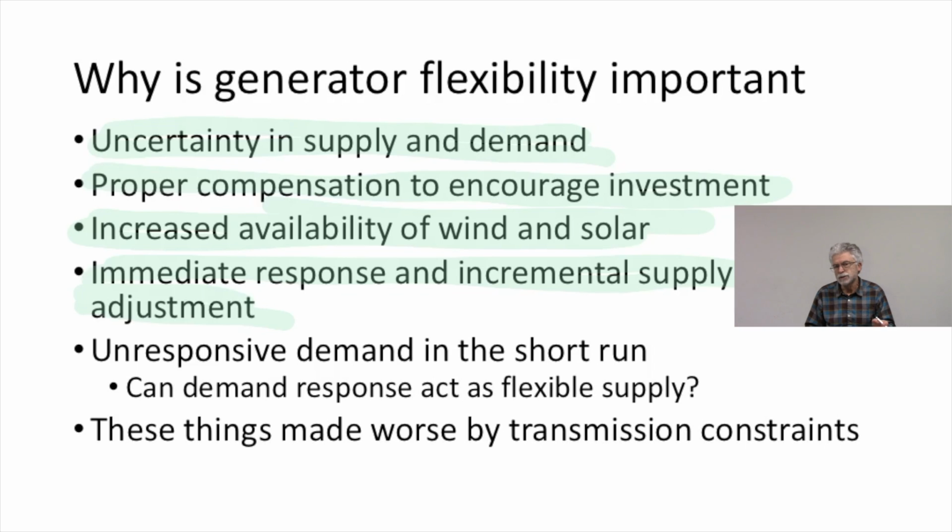But it also leads us to think about the possibility of inducing greater flexibility in demand by having tariffs that match the cost of providing grid services more closely. We can think about having demand that responds more readily to the other conditions on the grid. So we might even think of demand itself as being a flexible tool for managing the grid.